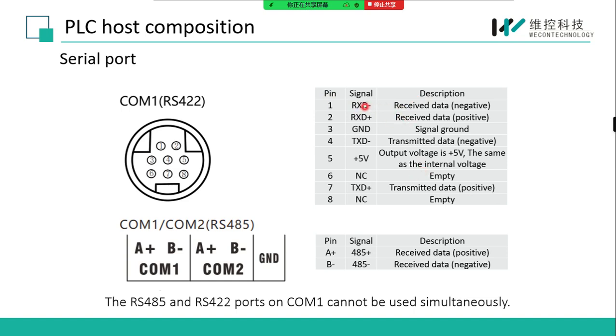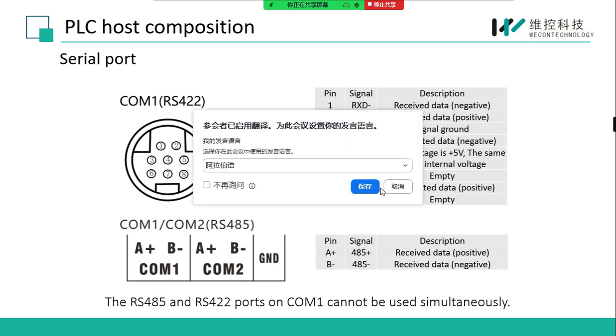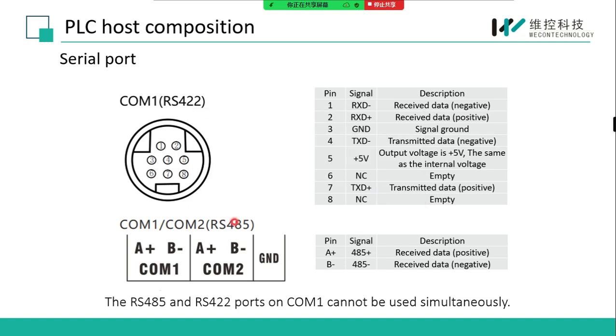It shows each pin's signal and description. And just one thing to remember, you cannot use this port and the RS485 port COM1 at the same time.